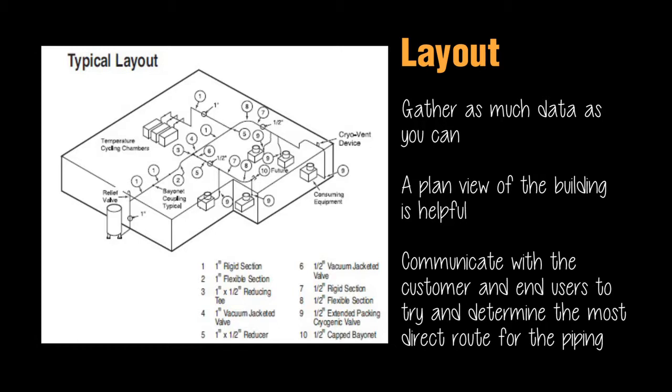Something to keep in mind when designing systems is that for every 10 feet of rise that the system increases from the tank supply point, an approximate 4 psi of supply pressure will be lost.